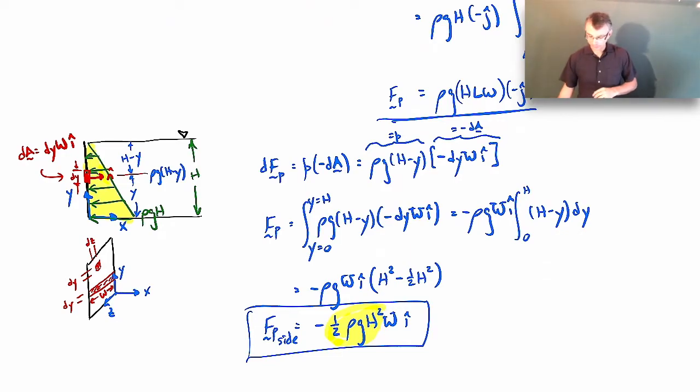All right. Now we found the resultant force, or the net pressure force acting on the surface. Now what we need to do is find where that pressure force is acting, right? So it's acting somewhere on that surface. We just don't know where yet. The way we find that is we balance moments on the surface. So we want to make sure that the moment caused by the distributed pressure force is the same as the moment we get if we replace it with a resultant force. So let me redraw the picture here.